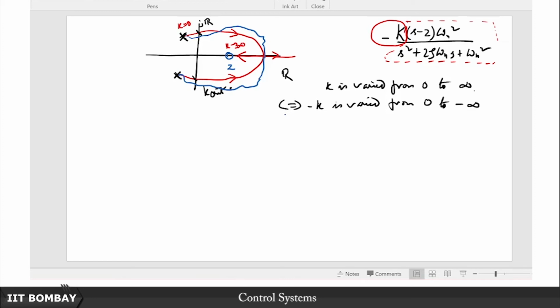So basically one feature of this right half plane zero, if you recall from our studies earlier, is that there is an initial undershoot. Even though the final steady state value is in the same direction as the applied input, the initial response is in the opposite direction. So this is a trademark feature of a non-minimum phase response. We've already studied this and shown you that this indeed happens.